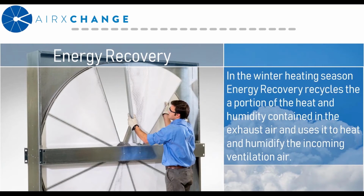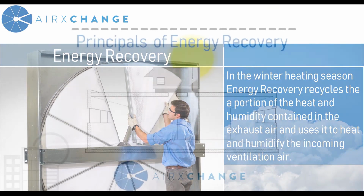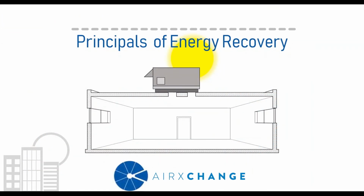So just as a refresher, energy recovery is used in the wintertime to recycle the heat and humidity contained in the exhaust air and use it to heat and humidify the incoming ventilation air. Fairly simple process. Looking at a typical system, the outside air comes into the unit and is heated by the primary heating and cooling element to a temperature that is suitable to be delivered into the space.